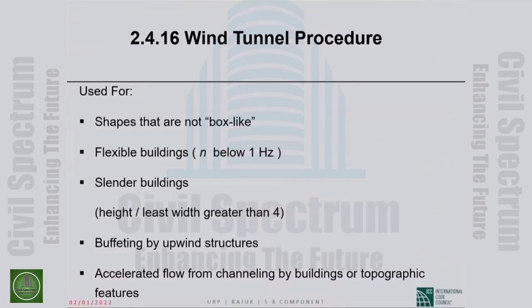So the wind tunnel procedure is used for shapes that are not box-like, for flexible buildings, for slender buildings, for buffeting by upwind structures. So upwind structures may do things to your structure, and that has to be captured. Accelerated flow from channeling by buildings or topographic features.